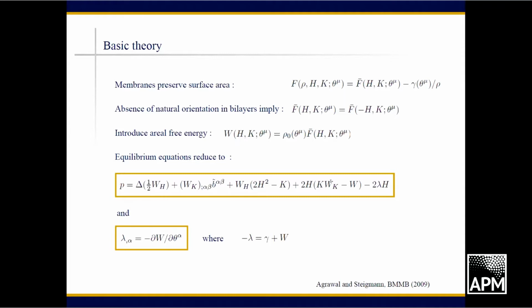W here is the bending energy. If all terms involving W are suppressed, then we recover the classical capillarity equation, that the mean curvature is balanced by the pressure. And lambda is effectively this Lagrange multiplier, a combination of the Lagrange multiplier with the energy that's constitutively indeterminate, must be determined simply from the boundary value problem that we wish to solve.